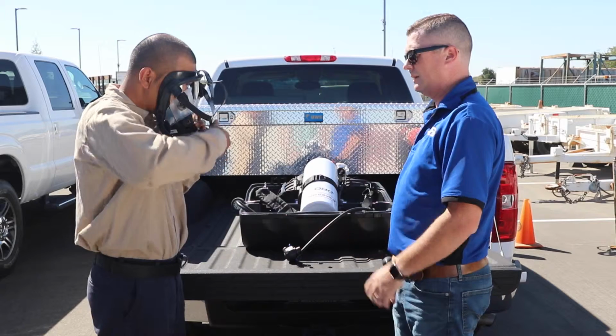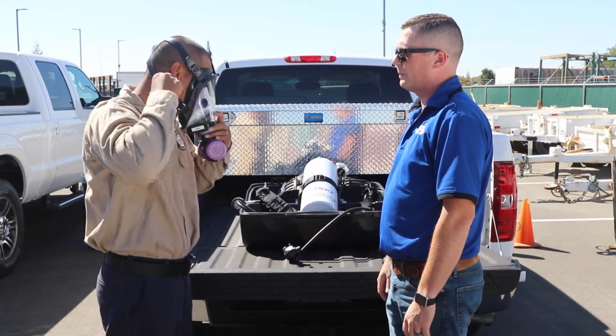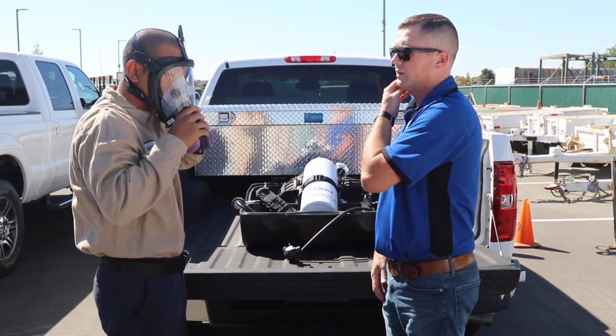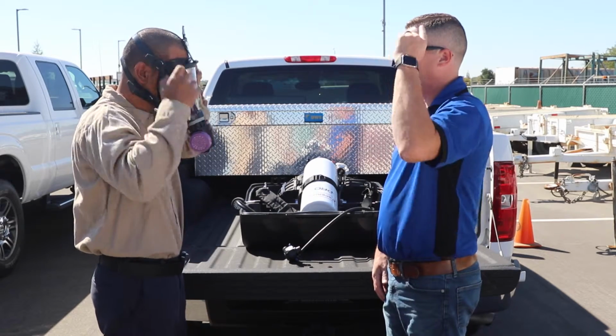Self-contained breathing apparatus, or SCBAs, are atmosphere-supplying respirators that supply a breathing air source that you can carry with you. These respirators come in 2 types, negative and positive pressure. A negative pressure respirator is one in which the air pressure inside the face piece is negative during inhalation with respect to the ambient air pressure outside the respirator. Examples of this would be your dust masks and half or full face respirators. The positive pressure type is one in which the air pressure inside the face piece exceeds the ambient air pressure outside the respirator. The SCBA is a good example of this type.